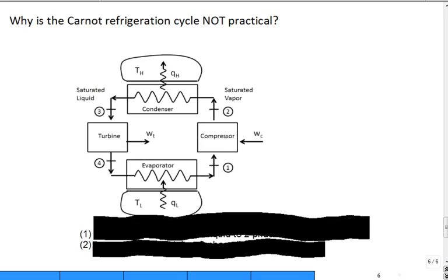Okay, let's say that we can get pretty good at making a compressor such that it's not necessarily irreversibilities like friction. We can minimize the friction. That's a good one, that's a real one, but I'm thinking of something else. Give me another one. But the condenser can go in with the same T and go out with the same T. Actually, the condenser could do a pretty good job. If I fed it saturated vapor, it would come out with saturated liquid at constant pressure. That would be okay. Somebody else.